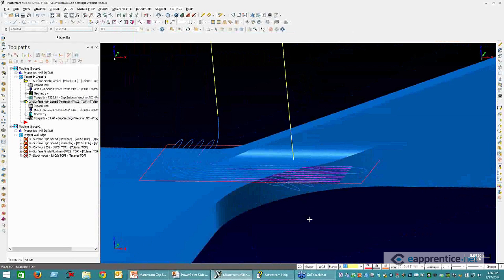I mean, there are different depth controls, but they're kind of treated separately in my mind from the gap settings. Gap settings is all about, does the tool retract or not? Okay, fair enough. And then those depth settings, you were basically setting a range there for that minimum and maximum depth, just in between those two values. Yes. Very good. So, Joseph, if you have a follow-up question to that, just go ahead and type it in.